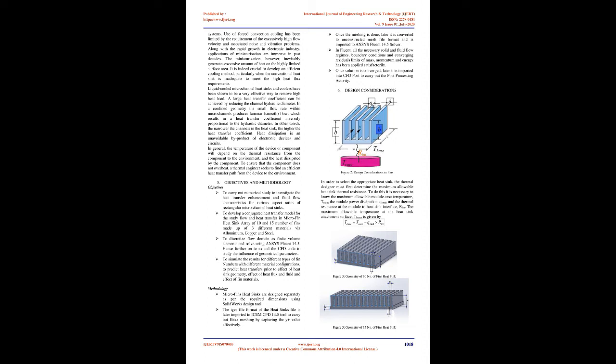Zeeshan and Majeed [16] have critically examined the non-Darcy boundary layer flow of a non-conducting real fluid. The analysis was carried out with magnetic ferroparticles over a permeable linearly stretching surface, taking into account the ohmic dissipation along with mixed convective heat transfer. They converted the existing governing partial differential equations into nonlinear ordinary differential equations by similarity transformation. They concluded that the skin friction coefficient increases and Nusselt number decreases with increase in ferromagnetic interaction parameter.